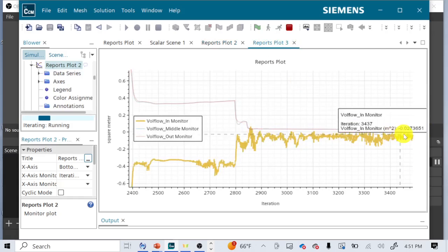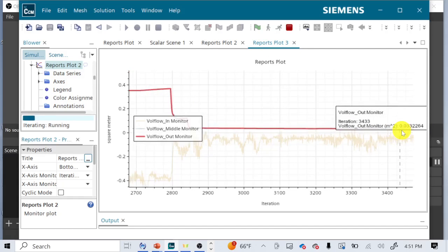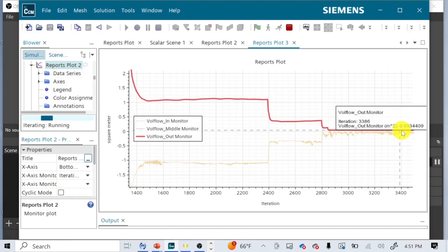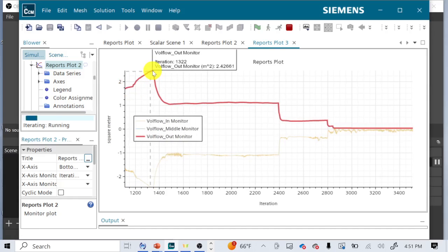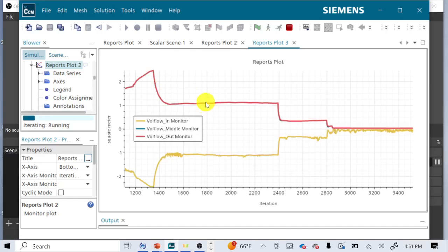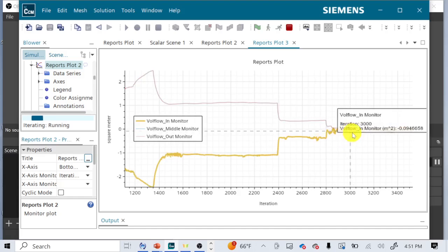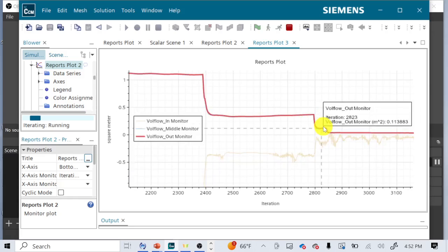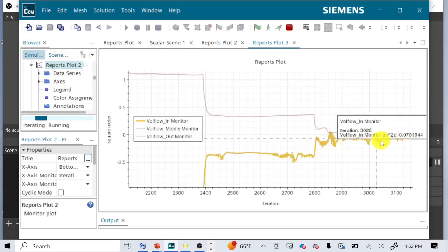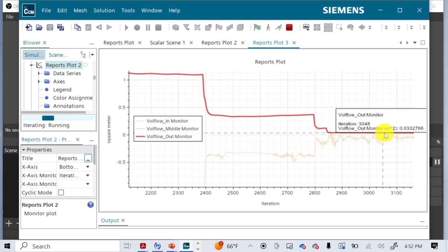And just to sanity check it, if we zoom way out, we can see what the step function looks like for this, because we started again about 1.7-ish. This probably would have made it up to 2.753 or so at a resistance of 0. Resistance of 10 was like 1.1. Resistance of 100 was like a third. We had a resistance of 1,000 very, very briefly. It looked like it was going to land somewhere around 1/8. And then a resistance of 10,000 brought us all the way down to like 0.03 cubic meters per second.